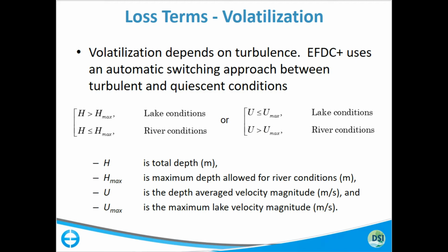Now, volatilization depends upon turbulence. And so right now, we have just implemented a relatively simplistic approach for determining which appropriate set of equations we need to use for the volatilization calculation. So what you do as a user is specify a maximum depth and a maximum velocity.